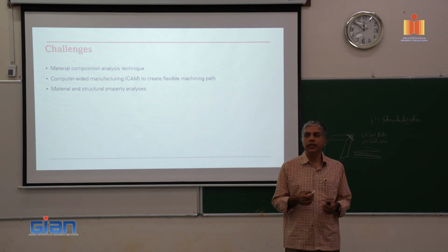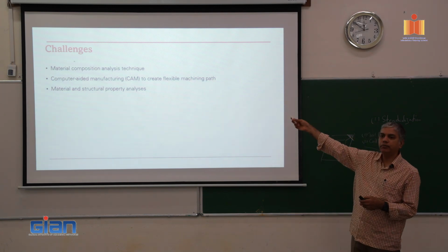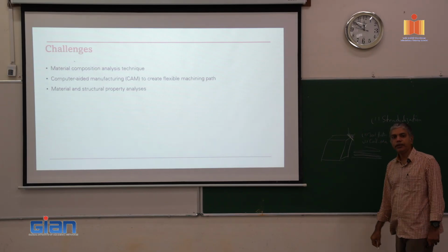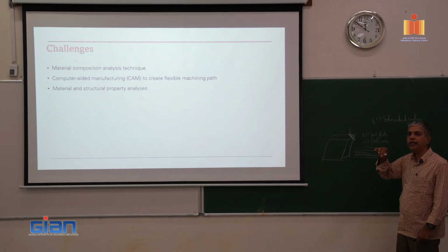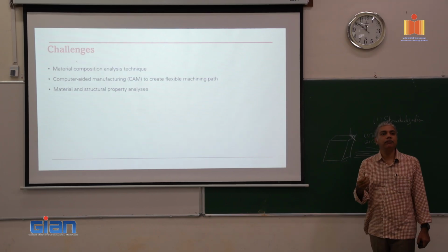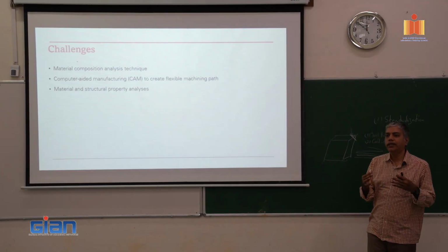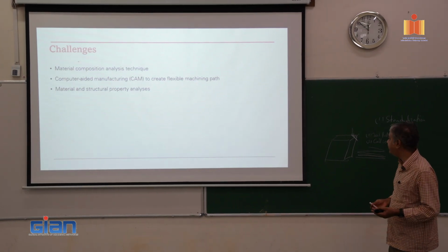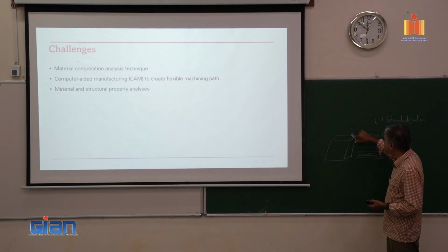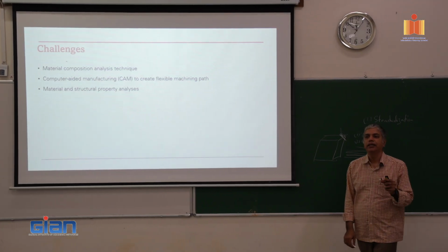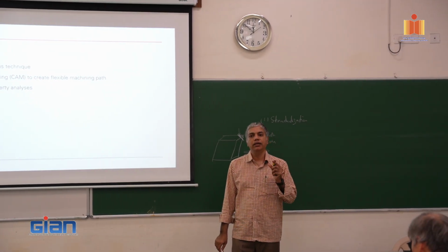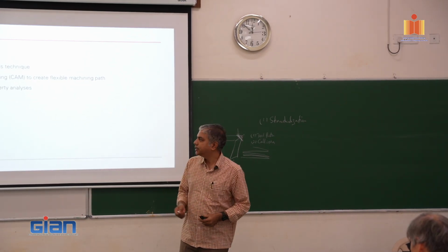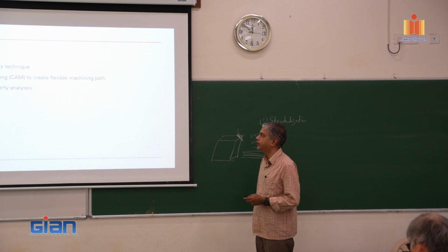So for every component you have to worry about the material, you have to worry about the tool path, but you also have to worry about the heat accumulation, what is the thermal history or the thermal situation at each component. Then if there is excessive heat generation, HAZ generated there, it may again lead to different properties or different behavior. Okay, so that is another challenge you have to keep in mind.